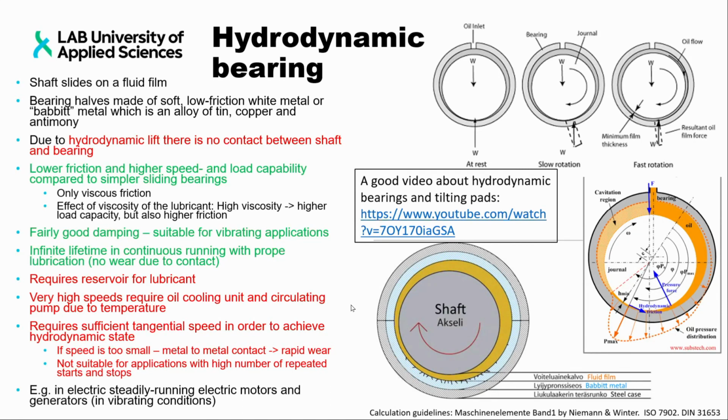Another good side is that because there is no touch between the components, it's basically providing infinite lifetime if you have continuous running operations. With the proper application, there's never touching between the rotating part and the static part, and it will never wear out. When I was working in an engineering company, we had one case in which we needed to